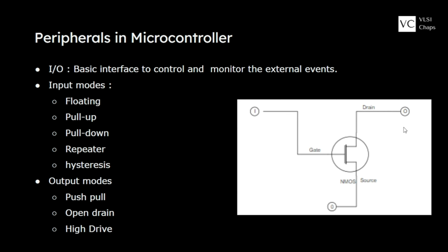What is the use case here? When we want to check each and every output of this pin, or we want to check whether a specific event is being executed on each and every pin or not, we can use those pins as open drain. The reason is these pins are not giving any effective output when applied as a zero logic.